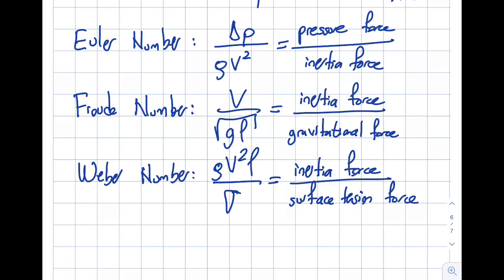Okay, this Weber number is important for flows when the surface tension has implications. In the majority of large diameter pipes, the surface tension is not an important player. Okay, however, for capillary flow or small microfluidics, nanofluidics type of applications, this number is very important.